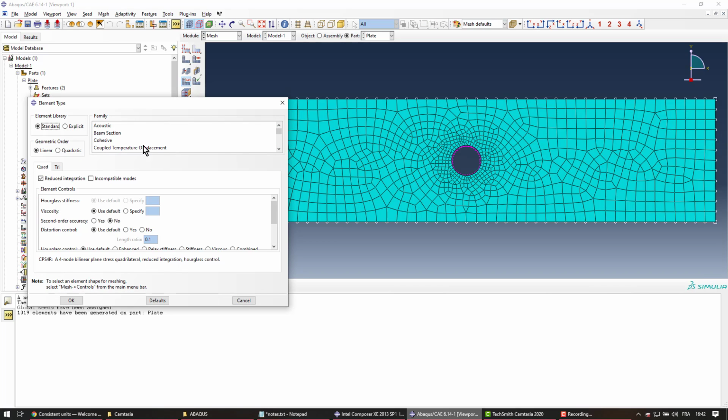Click on it. And then here I have a few options, but there are not so many that are useful for us. I'd say here we would hesitate between plane strain or plane stress. And this problem is a thin plate. We haven't defined a thickness yet. Let's say it's going to be 1 millimeter thick. So clearly it's a plane stress situation.